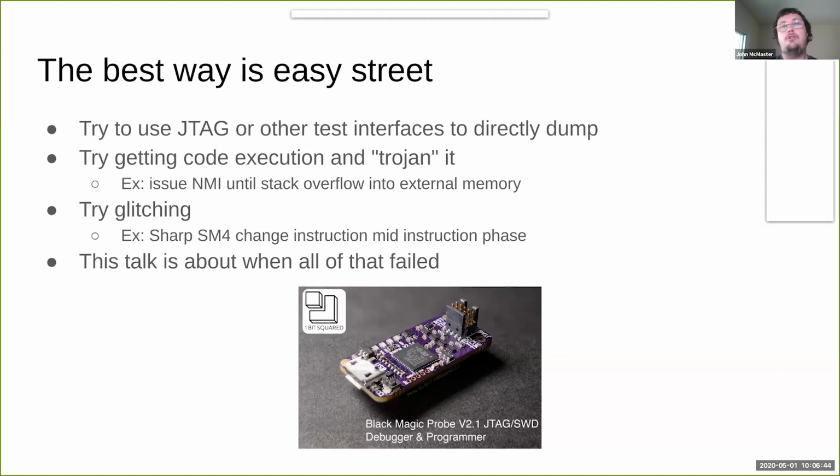And if you were able to generate interrupts, say non-maskable interrupts that you could just keep stacking, eventually you can build up so many interrupts that you'll actually overflow all of the memory and sometimes go into external memory. And then if you stop the interrupts and they stop popping the stack, you can basically control the instruction pointer as the stack starts getting popped and execute in external memory and execute your own code. And so that's just one example of how you might get code to execute on a protected device.